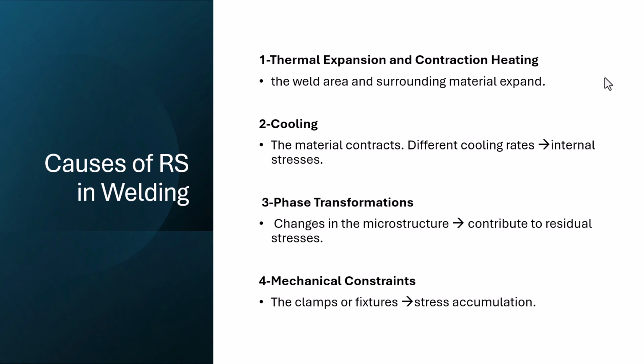Alright, what causes residual stresses in welding? The first and foremost is thermal expansion and contraction. During welding and cool down, the welded area and the surrounding material expand and contract due to the rapid heating and cooling. The second one is cooling. The material contracts during the cooling, and the different cooling rates of different zones of the material, as shown before, cause internal stresses and residual stresses.